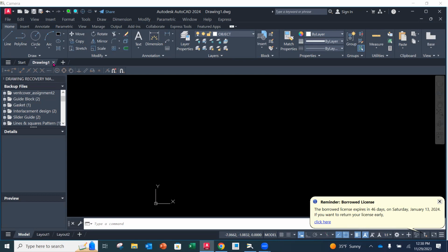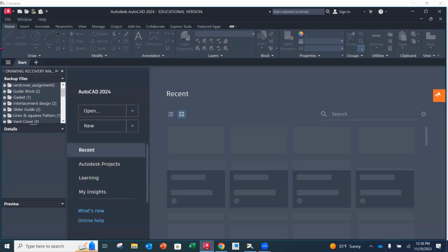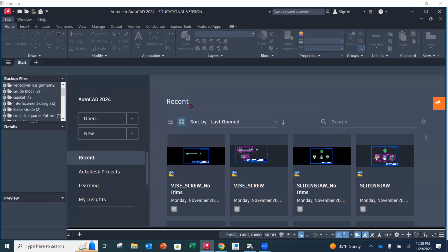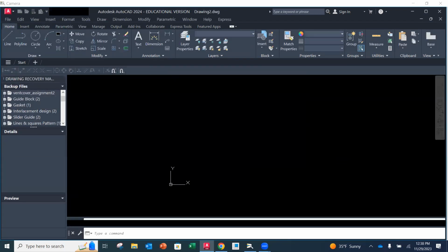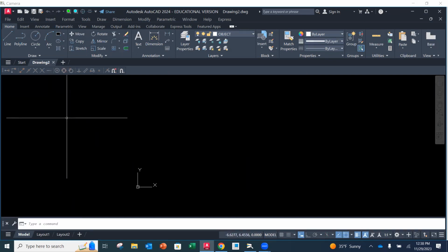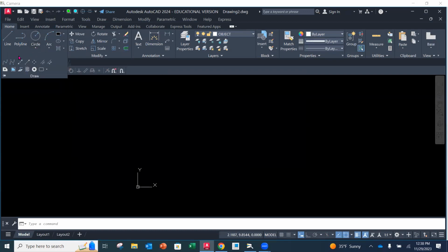So I'm going to close that. And so when we are in, I just want to start a new drawing, and I'll just take that one. That's fine. Get rid of that. There we go. So what you'll do is you'll create your points. All right. And then underneath the draw menu right here, here is the spline fit. Okay. And now you can either pick points or tangencies.